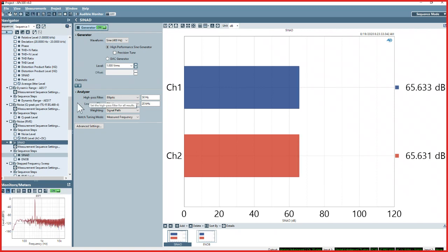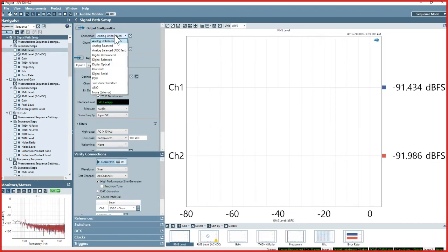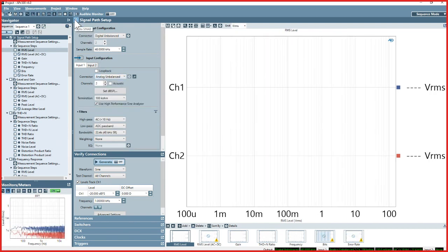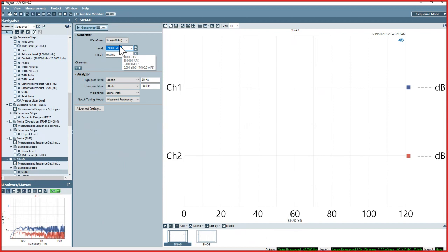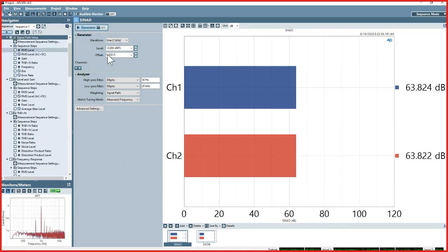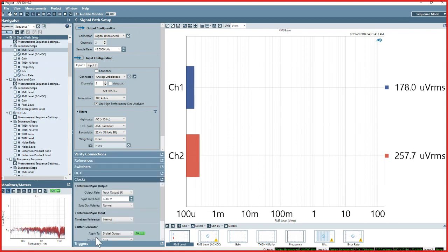And actually for this device, let's look at SINAD on the DAC. And let's do this at 1 kilohertz. Oh, and let me disable the jitter generator, or this device is going to look much worse than it actually is.